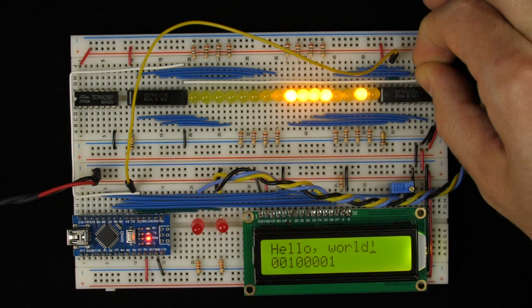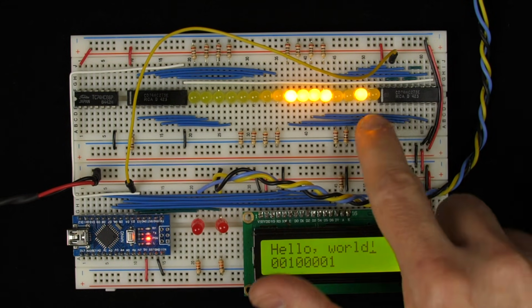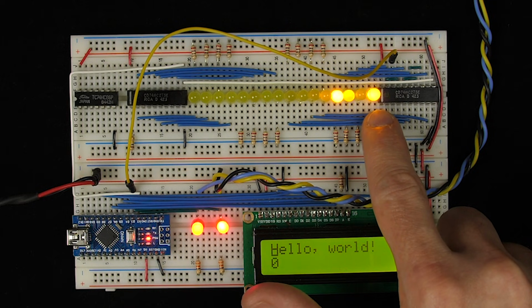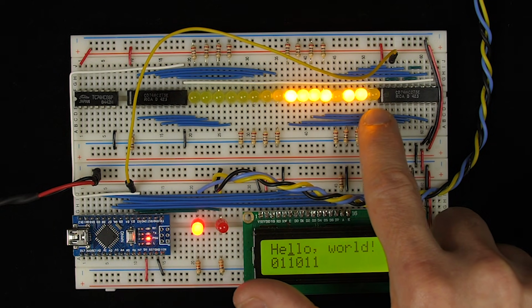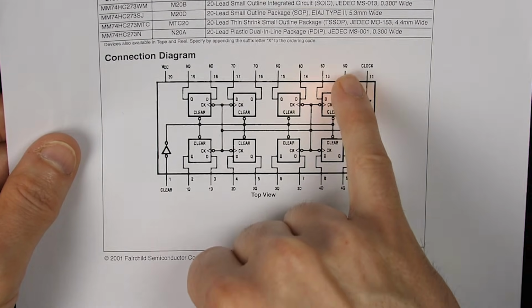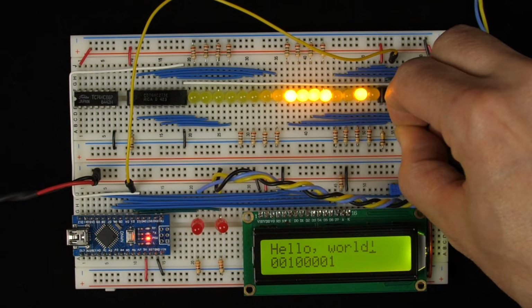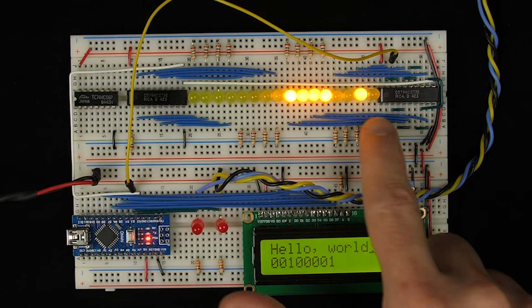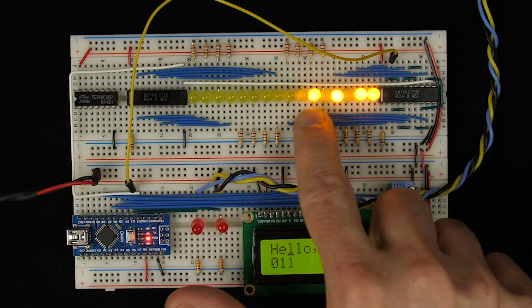So we can keep going, and basically I'm just going to connect the output of each flip-flop into the input of the one next to it. So at this point I've got the first 4, so let's just test that. And yep, it looks like in those first 4 we see data moving from right to left. So that looks good. So I'm going to keep going. Now the output of this one's got to go down to the input of this. Okay, now I think I have the first 8 hooked up, so let's reset this and see. Yeah, it looks like we're shifting along those first 8.